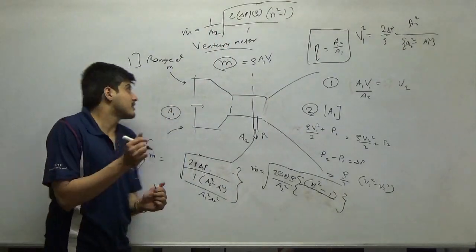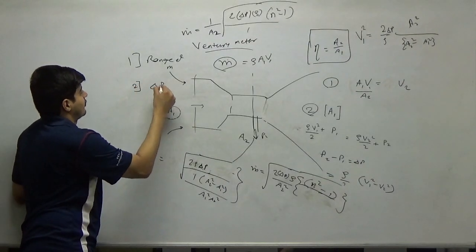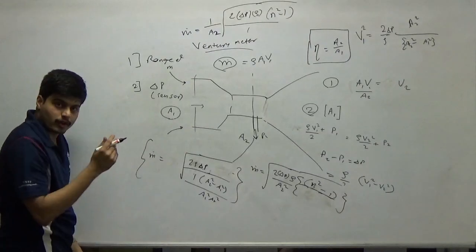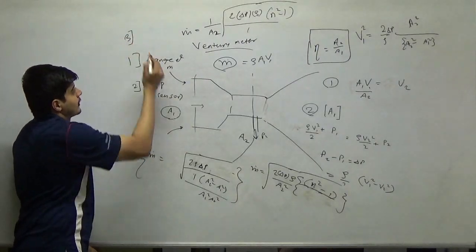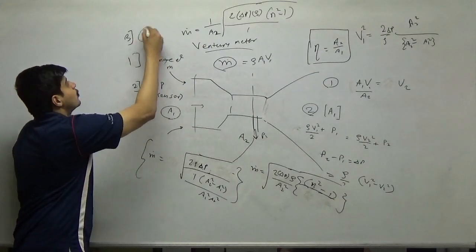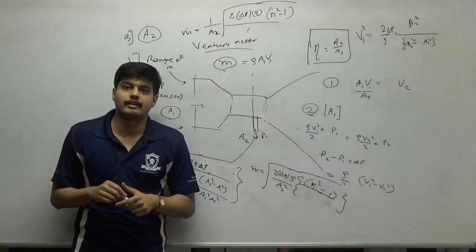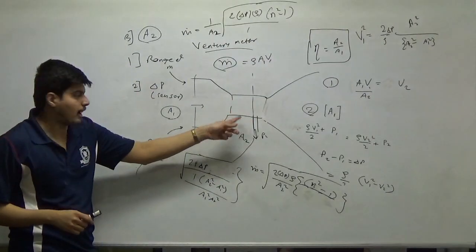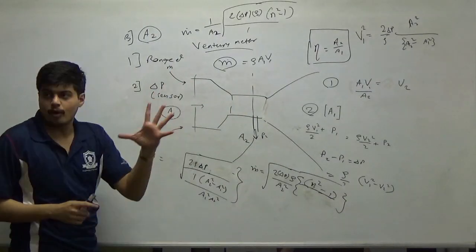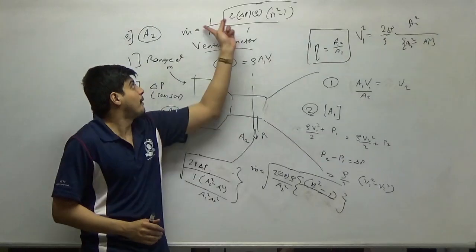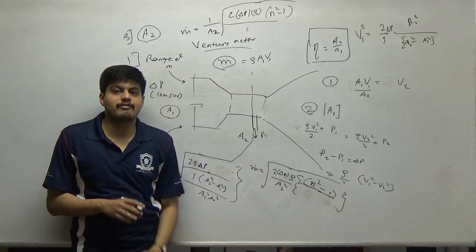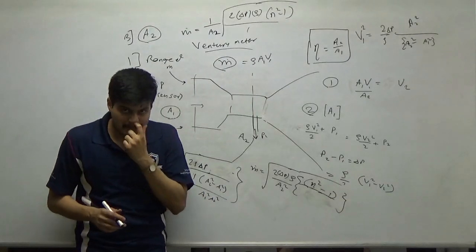So the three factors that govern your accuracy are the range of mass flow, lower or larger, which your data might be needed for; the sensor accuracy with which the delta P is being measured; and A2, the least area itself in the venturi meter. Better the handle you have to eliminate these capillary effects, or the ranges of lower constrictions, or the pressure errors, better accuracy you will get in m dot. That's all about a venturi meter, which is a very important tool in aerodynamic experimentation measurement.